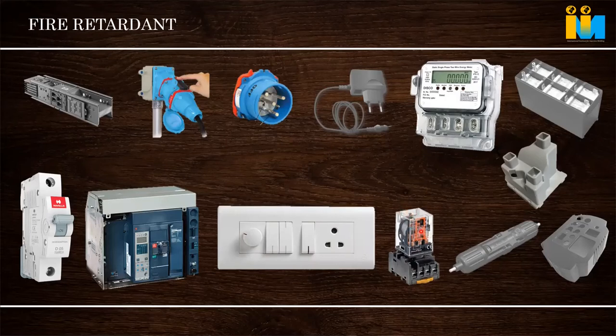Or in this case, polycarbonate copolymer is used because some relay manufacturers make this relay cover at 1 mm thickness, and they want a V0 at 1 mm. As I told, normal transparent polycarbonate will not serve the purpose. Then they have to go for a special copolymer which can give a V0 higher flame retardant rating at a lower thickness.